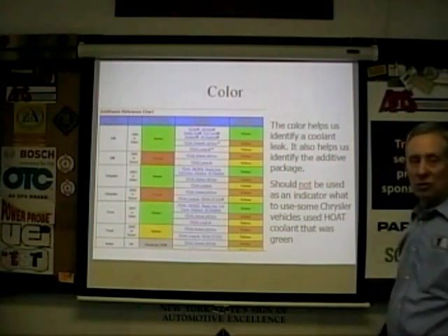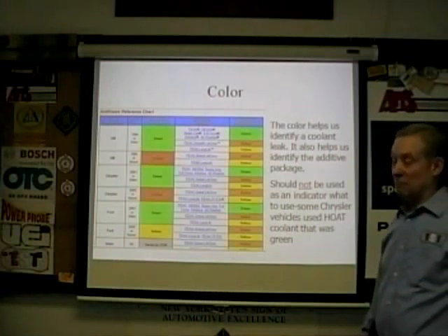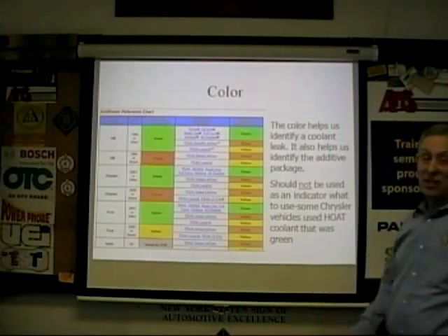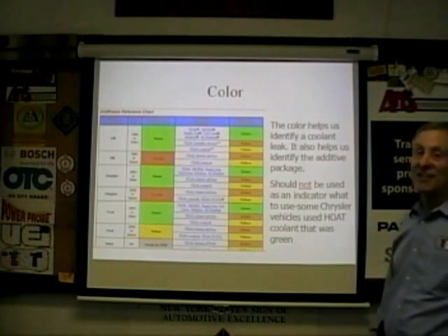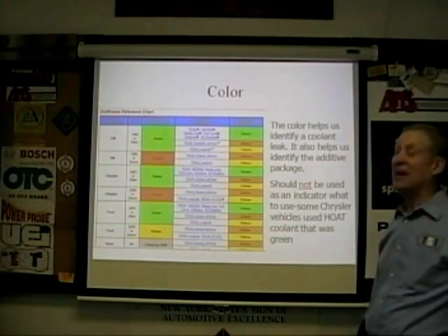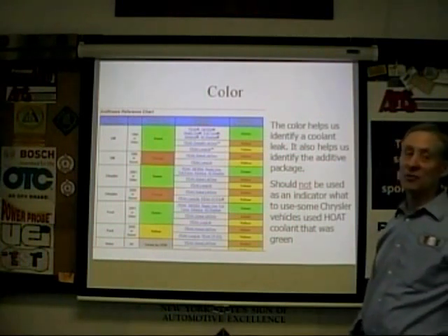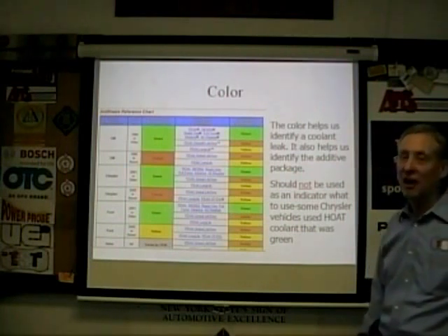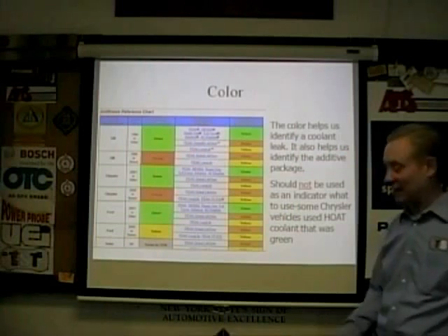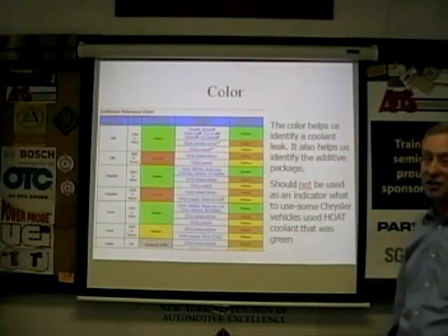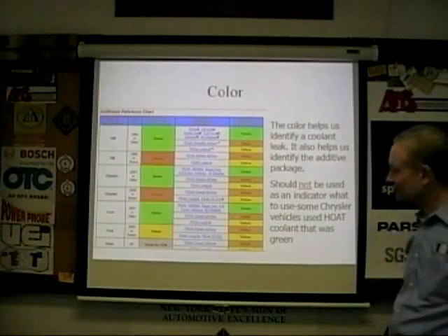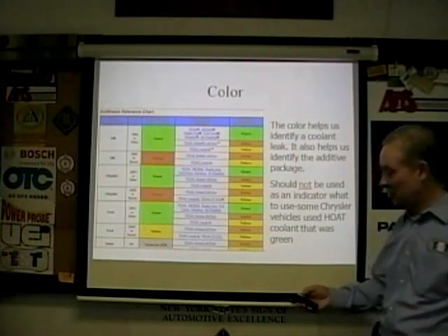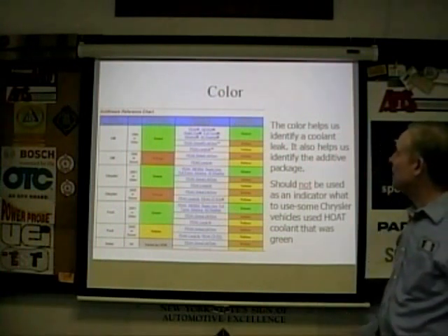So Pierre, you can use like a black light type thing, like an air conditioning? Most, yes, absolutely. It's not exactly the same frequencies as air conditioning necessarily, but most manufacturers of antifreeze or coolants today put some type of UV dye in the coolant so you can see it. You've got to watch that your glasses are matched to your light. There are different frequencies of black lights, but it is possible to do it.